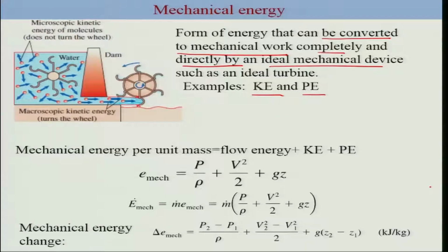Okay, the pressure, though, is not an energy, but when the pressure force acts on the fluid through a distance, it produces a certain work. Okay, and this work is called flow work, and for convenience we say it is flow energy, and we include that as a part of the mechanical energy.